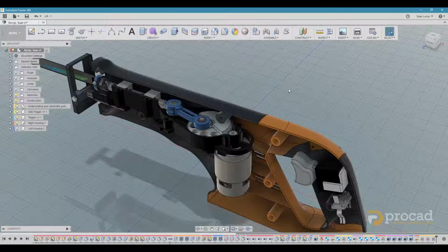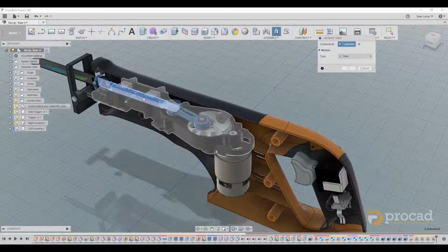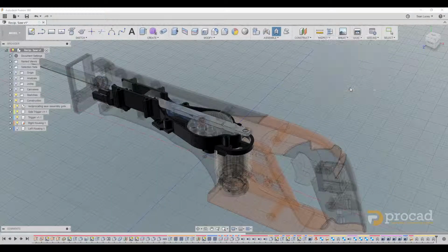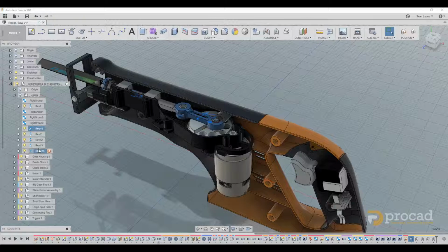Users can quickly and efficiently constrain geometry with an emphasis on component movement to ensure the components that make up the overall design work harmoniously together. Once your model is fully constrained, you can select your joints within the Joints folder and animate the model to show the full scale of movement.